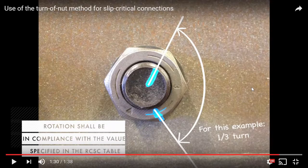So for instance, for this example, that particular bolt needed to be turned a third of a turn past snug tight. If you notice, you can see here was the mark that was placed on the bolt, and there was one nut right here. And then that wrench basically just yanked on it until it got that third of a turn, and that's prescribed tension. It's one of the easiest methods that's used.